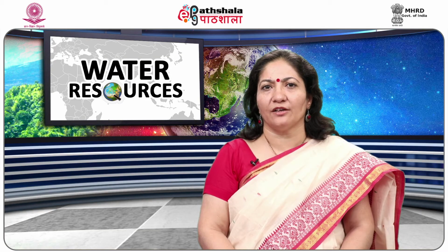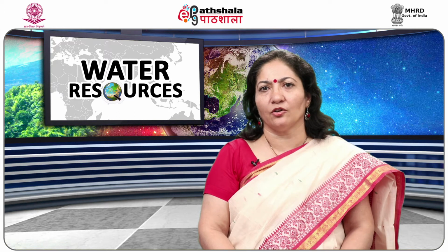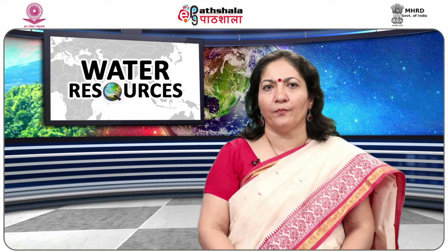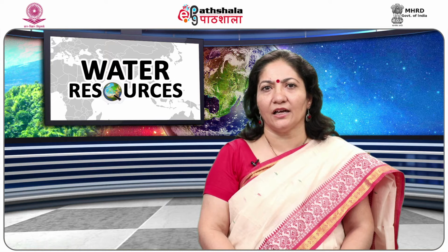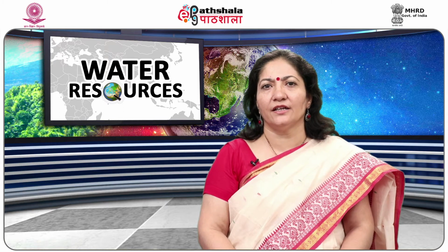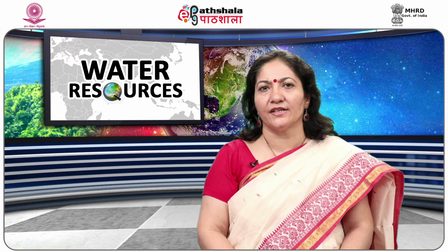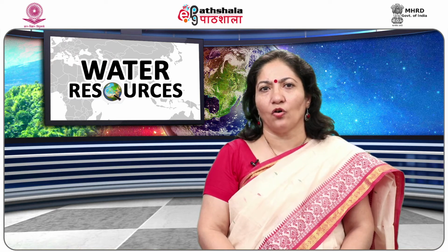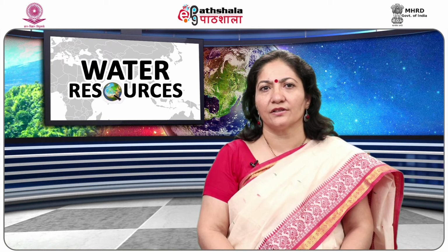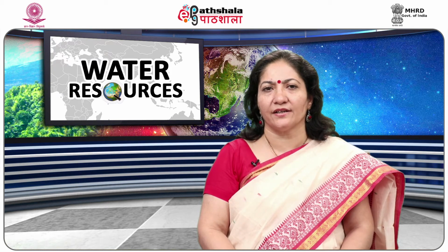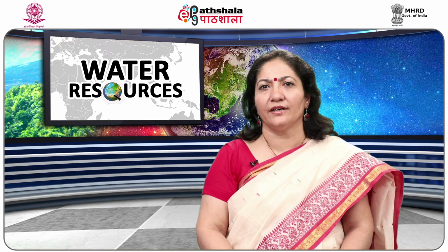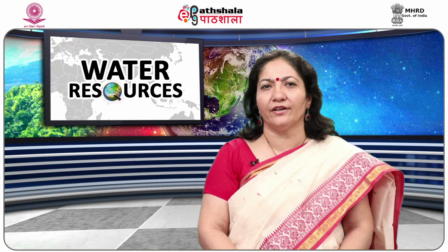Porosity is dependent on the type of rock which contains the water. In other words, the porosity depends upon the spacing, pattern of cracks and fractures of the rocks. In sediments, the porosity of the rock depends on the grain size, shape of the grains and the degree of sorting and cementation. The sorting or packing arrangement is most important in these rocks. The porosity of well-rounded sorted sediments is significant as they are almost of the same size. Poorly sorted sediments generally have low porosity because the fine-grained particles tend to fill the void spaces.